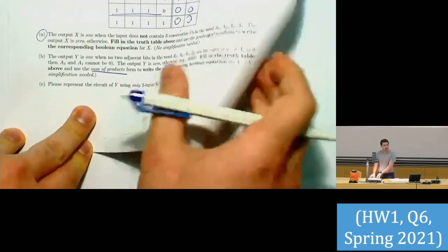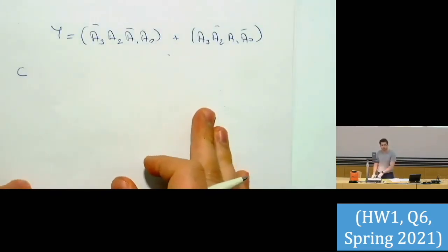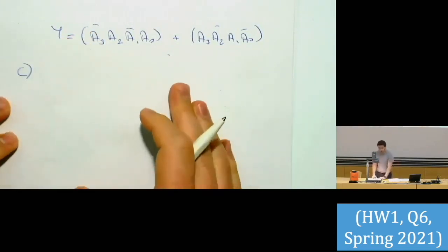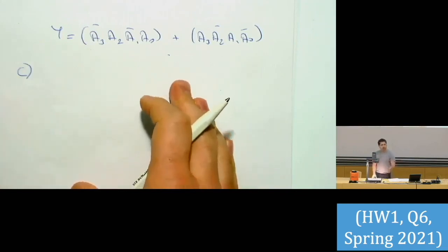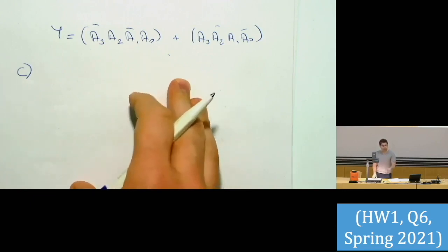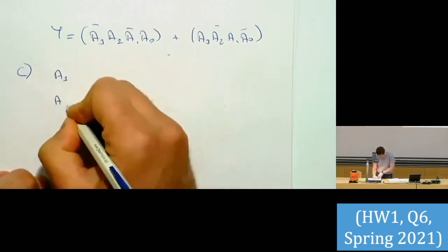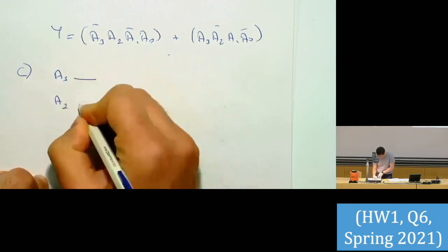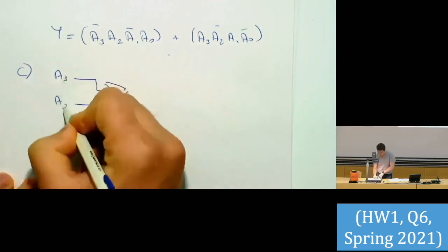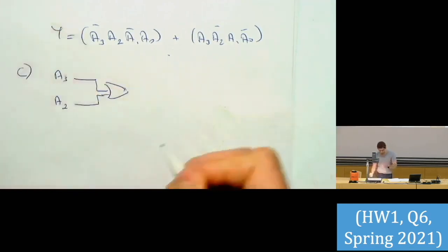I'll write the circuit in a very intuitive way, and also I'll show you the equation later. Very intuitively, for Y, I shouldn't have any 2 adjacent inputs equal to each other, right? So those are basically XORs, and those shouldn't be equal to each other. So this ensures that those 2 inputs won't be equal, or it will give 1 when those are not equal to each other.